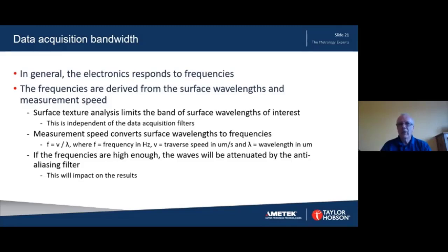For a given wavelength, the frequency will increase with the traverse speed, and therefore for finer surface finish, which often involves shorter wavelengths, it might be necessary to reduce the traverse speed to record these waves accurately.